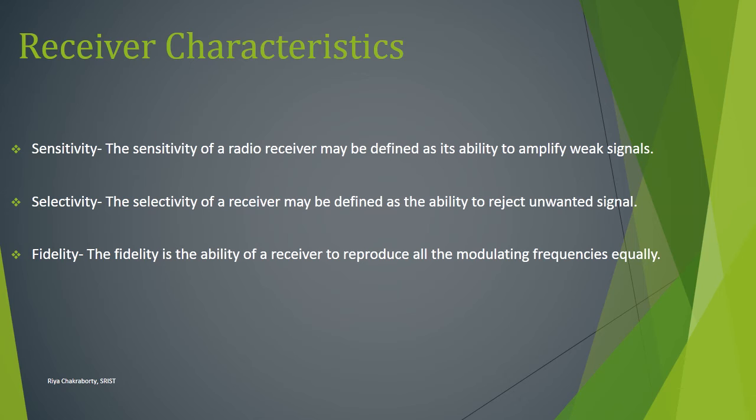Tracking of a superheterodyne receiver is also needed, because in a superheterodyne receiver the local oscillator frequency is made to track with the tuned circuits, which are tuned to the incoming signal frequency, as you see in the block diagram, in order to make a constant frequency difference at the output of the mixer. I think these all are clear to you.